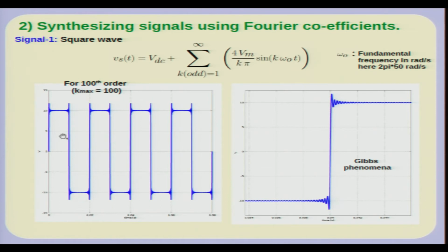You can represent this square wave as an infinite series of sinusoids. So, a periodic wave can be represented as a series of sinusoids, and as we have seen before, if you have a superposition of sinusoidal inputs, which this wave can be considered to be, then you have similar frequencies in the response as well, although different frequencies get attenuated or scaled to different extents depending on the nature of the filter, or the nature of the transfer function. I have been talking of low pass filtering, but you can also have high pass filters, etc. You can try some practice problems in which you have different frequency behavior.